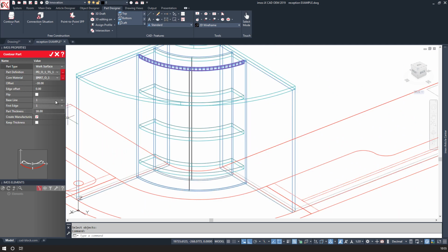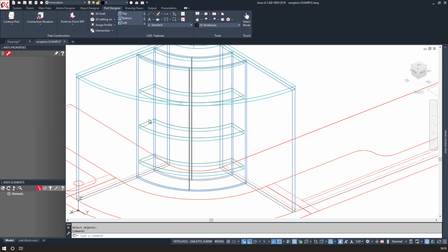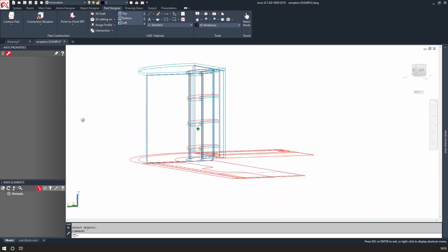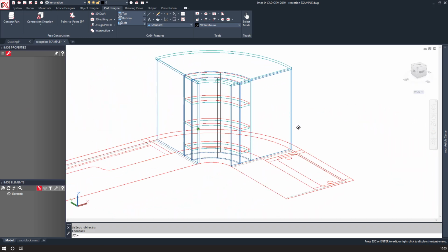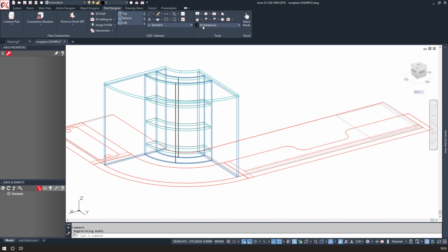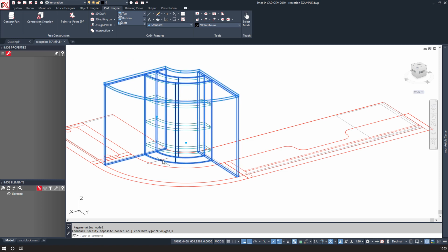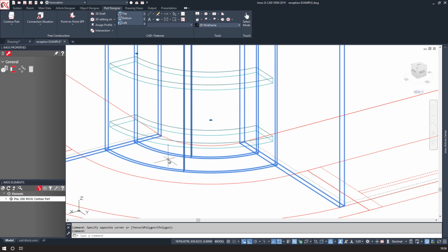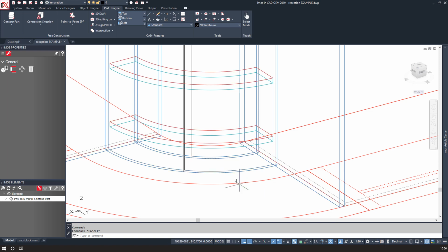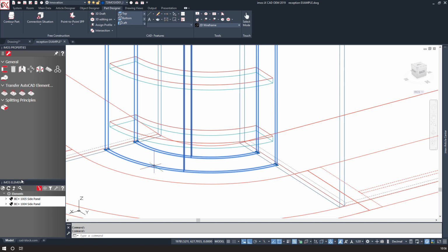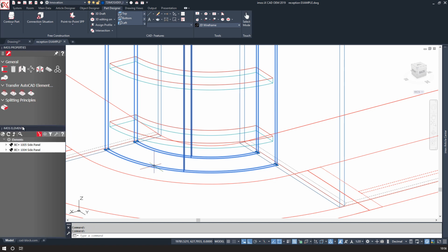So when it comes to assembling this piece, the production team can put some pins or brads, nails, screws through the 12mm flexi-ply into these curved sections to help keep its form, and then over laminate this by hand. There's lots of different ways of creating these parts. I'll make sure that these have a laminate surface applied to them so that you won't see the screws.